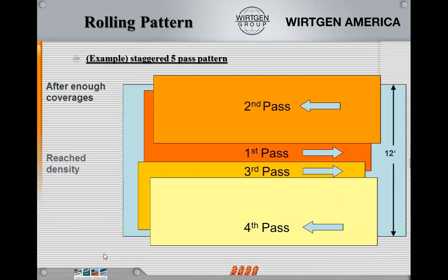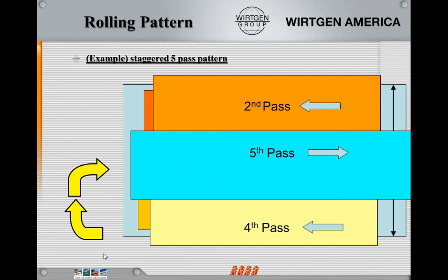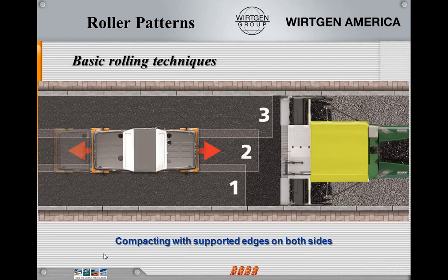most of the time everybody will go up the center. I always tell everybody, go up the side of the pavement that you struggle the most getting density with. Normally it's going to be the outside edge or the unsupported edge. But if you go on the outside edge on the downside, when you get to your next pass, you just need to keep going straight. You don't have to worry about moving back down or moving back up, whichever way you do it. Now you just keep going straight into your next passes. So it works out well.